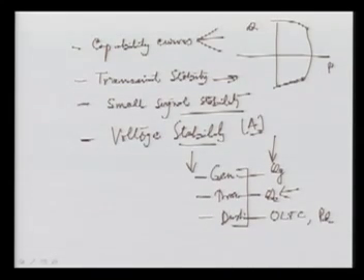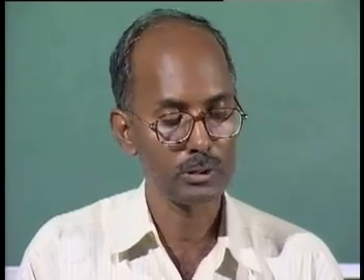So in total we discussed, starting from the capability curve, modeling of the synchronous machines, then we utilized the transient stability. First I used the classical model with the single machine infinite bus, then I went for the multi-machine system, then I discussed the various approaches to improve the transient stability, then I followed with small signal stability, and finally I discussed voltage instability where various methods were discussed.